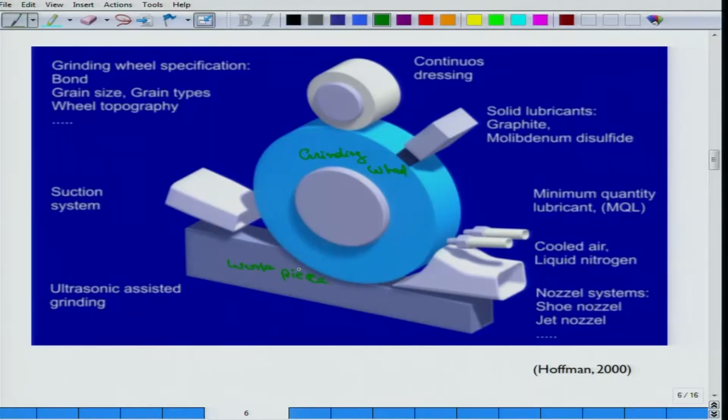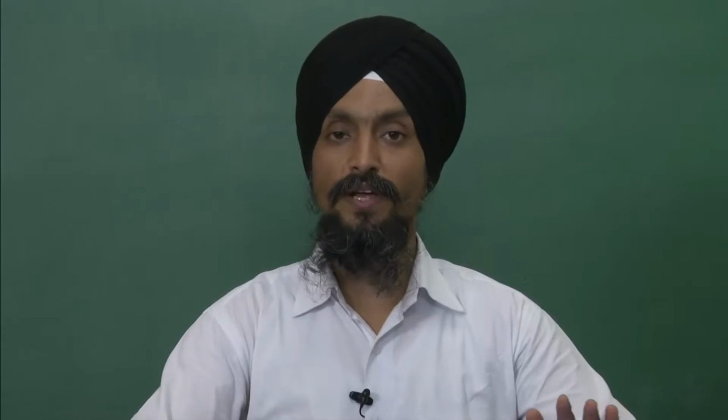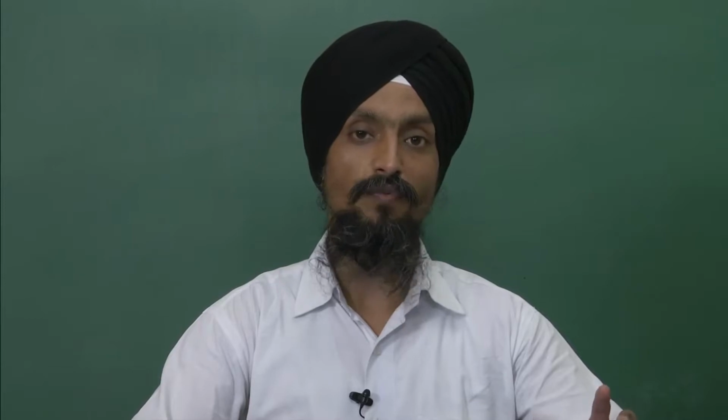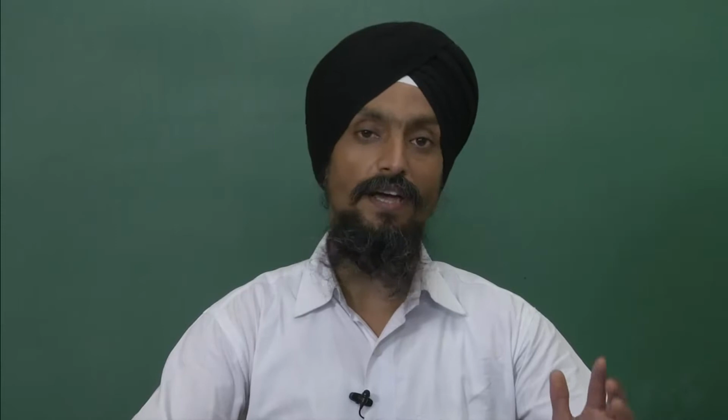Grinding is typically a finishing process after doing any kind of machining, for example, turning or milling. Grinding is the final process to obtain the final shape. The grinding allowance is always kept during rough machining. Maybe in milling, some grinding allowance is kept, and grinding produces finished surfaces. Depending on the type of surface finish required, the type of wheel is selected, and there are specific wheel abrasives that can machine specific workpieces.